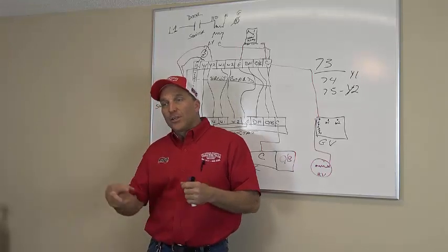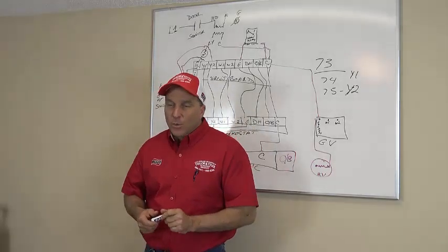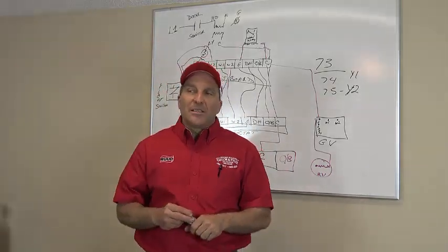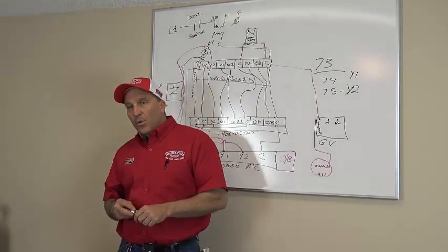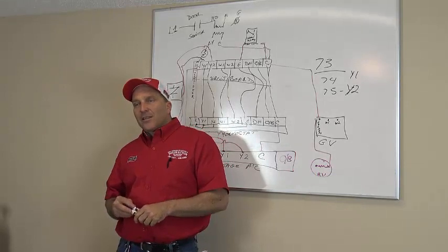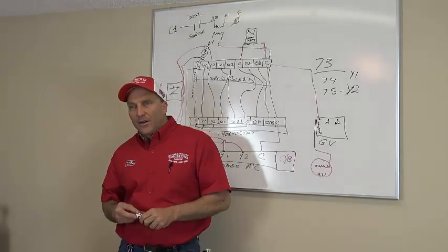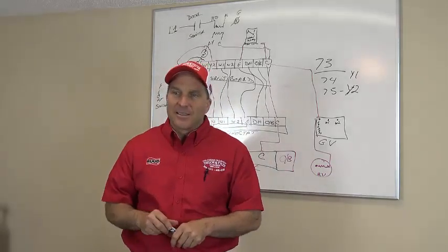That's why there's two additional wires going over to it, which is 18 to 22 DC voltage going to that solenoid, which comes from the circuit board. Then that energizes that solenoid valve, and you will actually hear that compressor kick into that second stage.